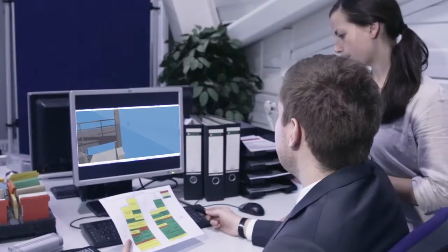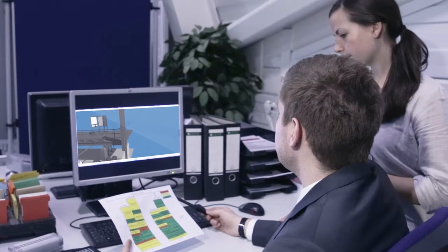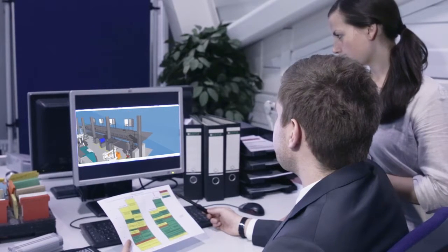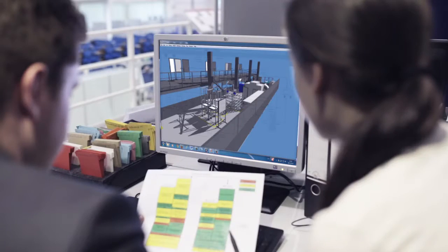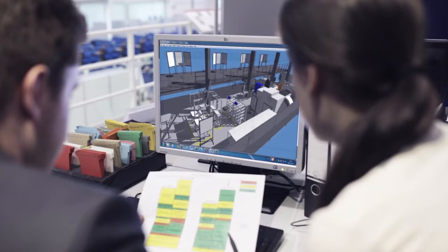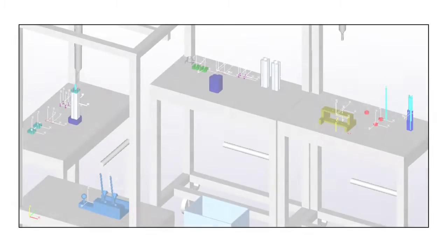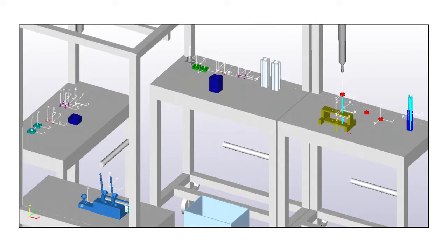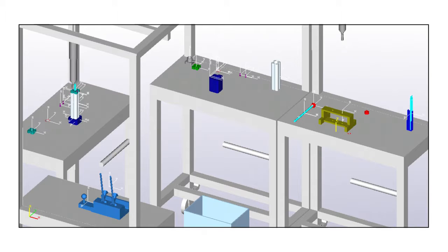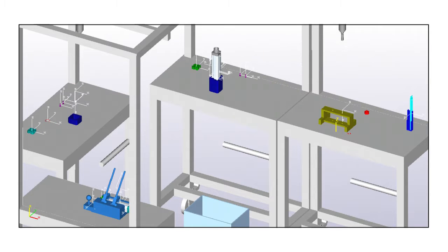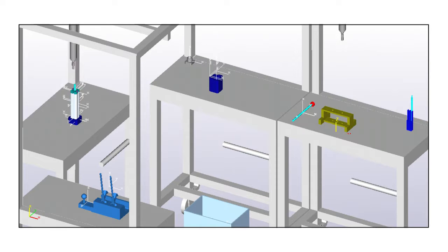Through the use of digital tools in the learning factory, the result of balancing the assembly line can be validated directly in a virtual layout design before the optimized assembly system is physically implemented. With the assistance of assembly simulation, many significant improvements can be visualized, such as the achievement of an even material flow, the avoidance of stock, and the reduction of transportation distances between the working stations.